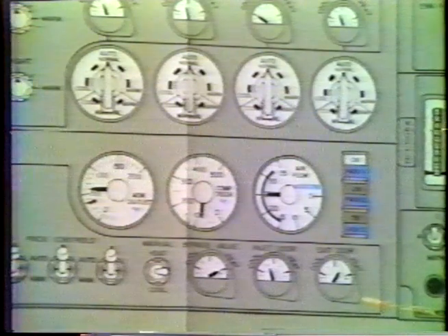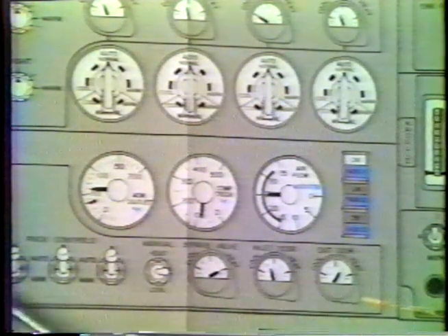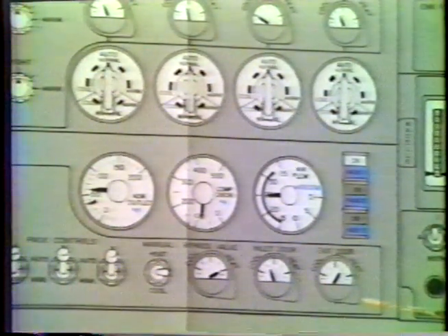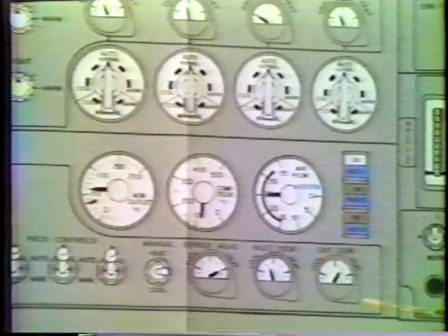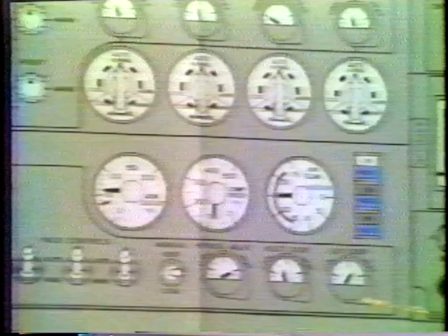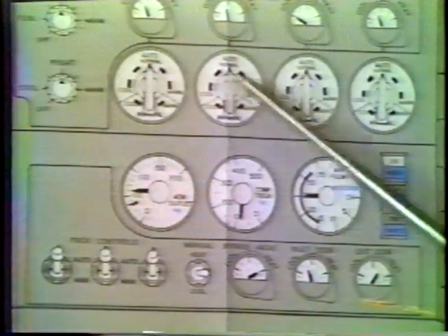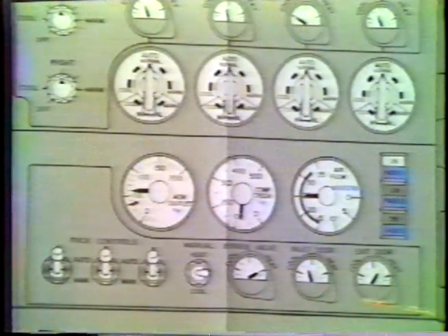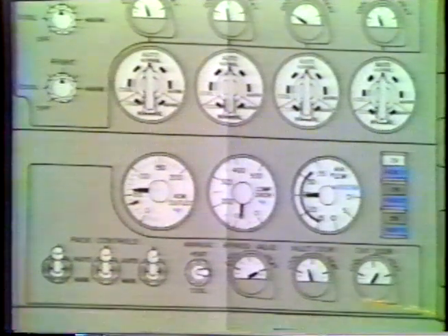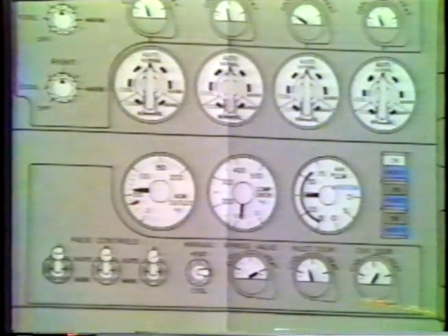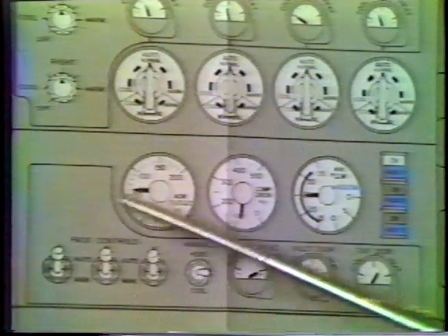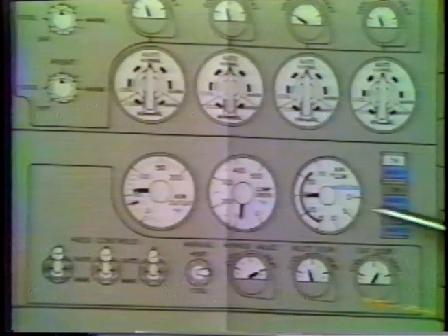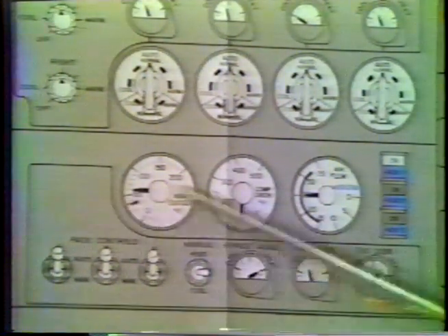Normally the PACs are operated in automatic. Automatic with these selector switches in the up position. This allows a small computer to meet the demands that are being called for by the temperature controllers above the PACs. We'll discuss that in a few minutes. Normal operation of the PAC, the 3 top gauges run approximately the 9 o'clock position.